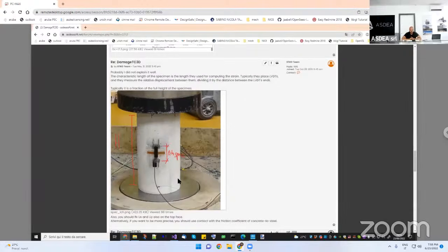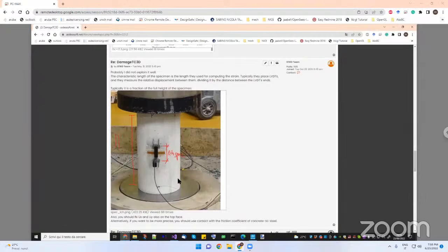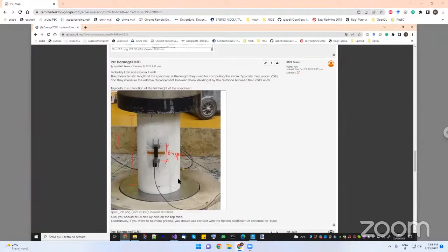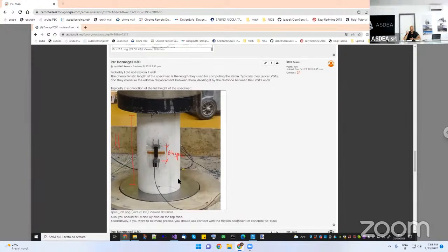That boundaries without regularization, you're talking about the boundary beams. Yeah. The boundaries are beams. If I understood correctly, you obtained a good result using the fracture energy regularization in the shell shear wall and no regularization in the boundary beams. Exactly. Probably this was fine. You know why? Because they gave you the specific fracture energy computed over a certain length, and then you discretize the beam with a size which is close to the plastic hinge size. In that case, the regularization is not going to do anything, okay? So probably that's the case.